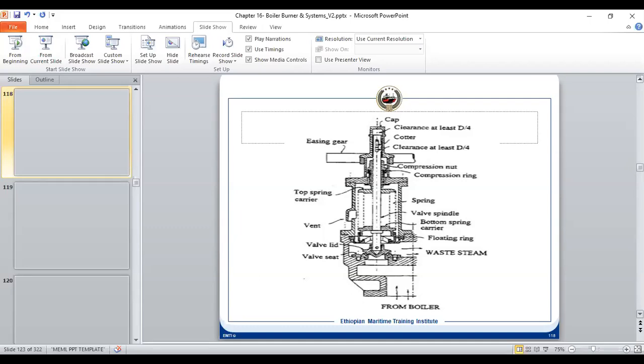If it is giving too much air, that means your secondary flame is cooling down. If it is giving too little air, that means the proper combustion is not taking place. So either way. Chief, sorry. Yeah, go ahead, please. If this draft is the one blowing the air to the boiler and it is excessive, how can it cause high temperature? No, if it is excessive, it will cool down the secondary flame. It will not be high temperature.